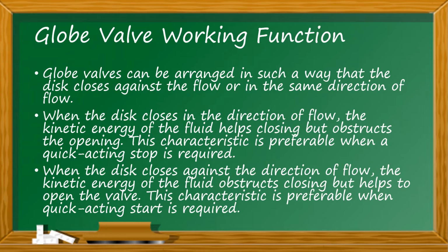If you want to close the valve instantly, then you need this type of characteristic. When the disc closes against the direction of flow, the kinetic energy of the fluid obstructs the closing but helps the valve to open up, and this characteristic is helpful for quick starting of the valve.